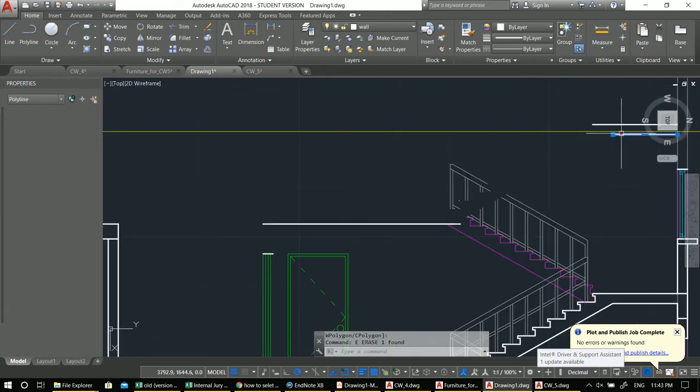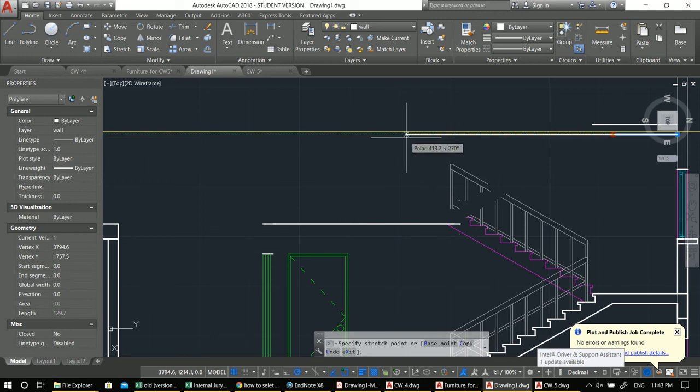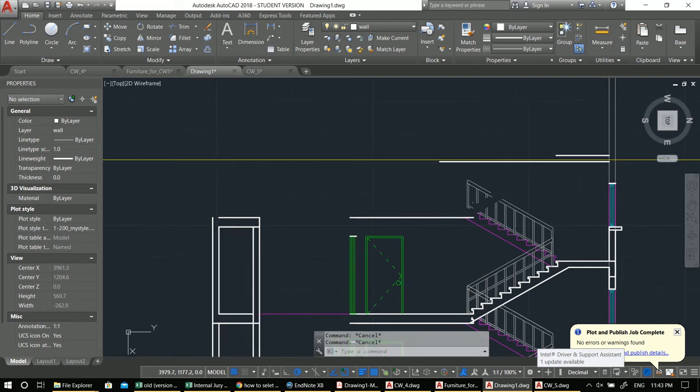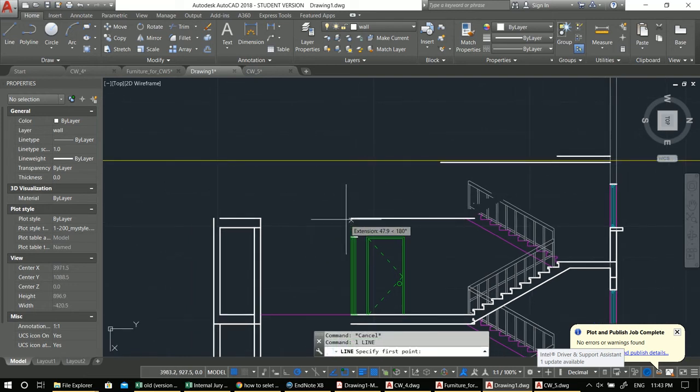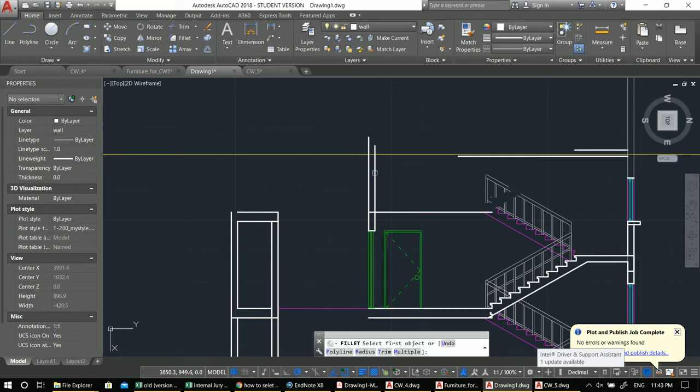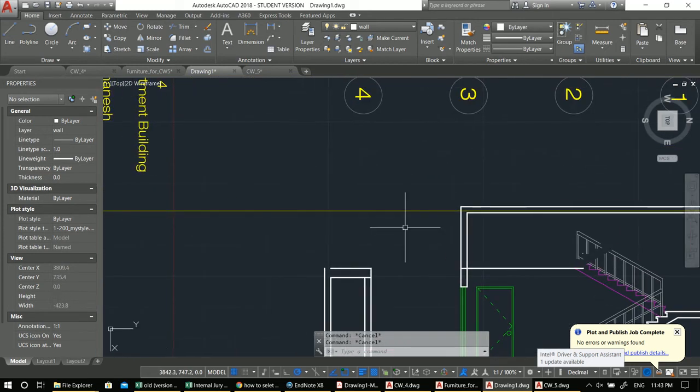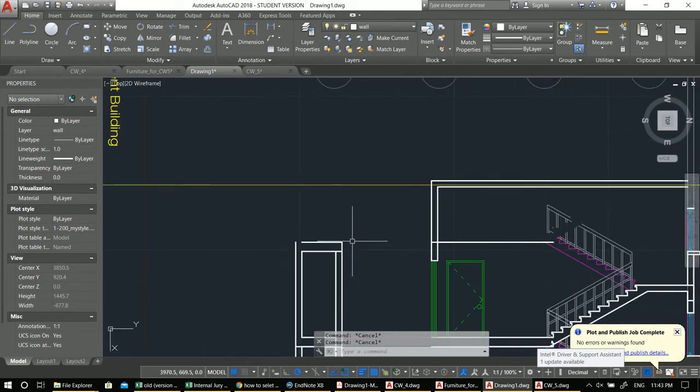So we will have a room for the staircase. If you have a last floor plan or a roof floor plan, you will find where it is. I'm guessing that it's similar to the staircase. So here I will have this line come up, this line come up, and then I will fillet it for now, because we have to add the parapet wall for the roof. When filleting, make sure that you're picking the longer side of the wall, and again for the elevator shaft as well. This will come up. It will not end there.